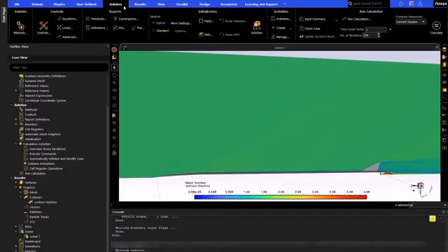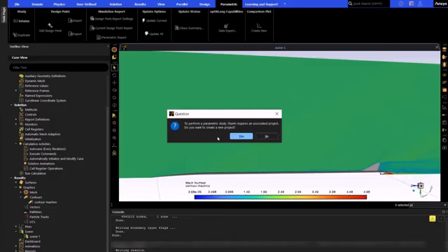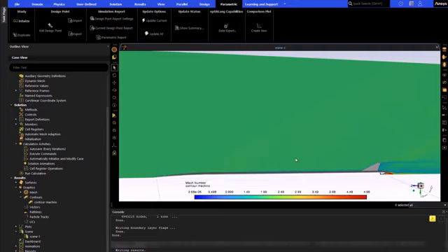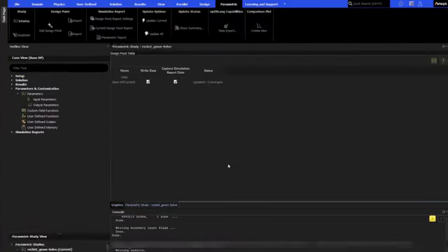Starting with the initial mesh from our Mach 2 simulation, we'll do a parametric study by selecting the Parametric tab and pressing Initialize to create the project workflow, and save it in the working folder. When running a parametric study, be aware that there is frequent reading and writing of case files, which is sped up in this video accordingly.